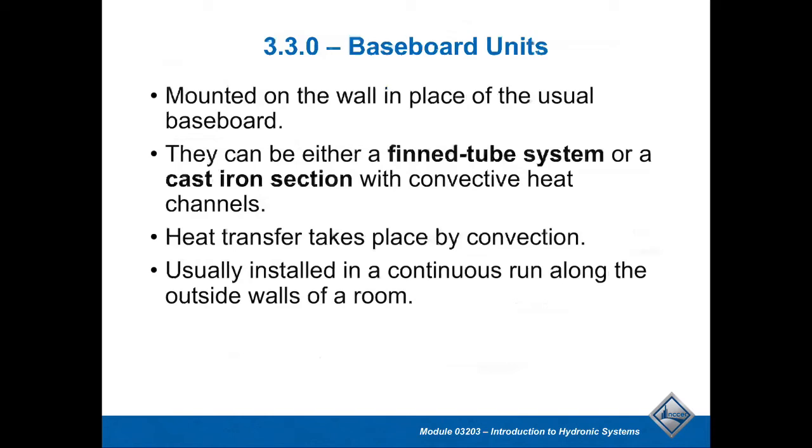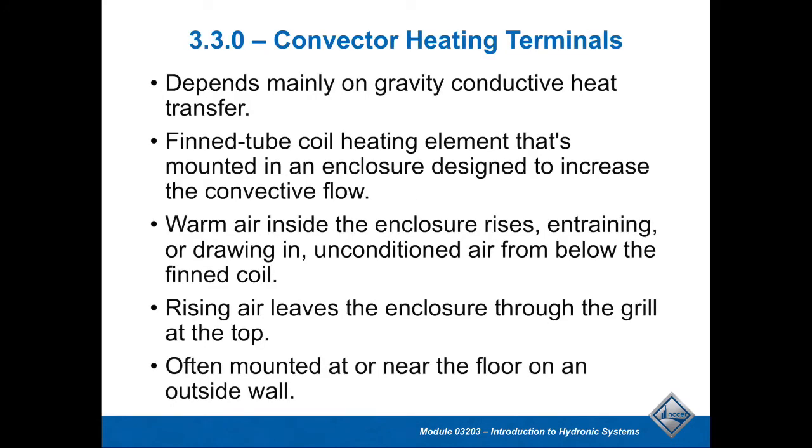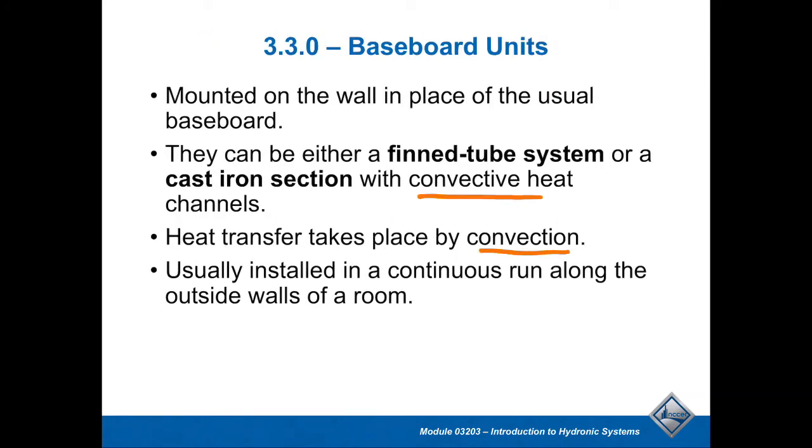Baseboard units. Normally we would install baseboard where the heat load is, which would typically be near an outside wall. You might as well put the BTUs where the heat is really needed. Most baseboard units also work on convective heat, very much like the previous convector heating units, so again, usually natural convection. In a series system, which a lot of residential jobs have, you typically have several baseboard units in series.